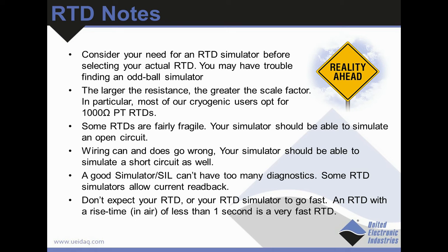Some RTDs are pretty fragile. You have to be a little bit careful. For that reason, your simulator should be able to simulate an open circuit. Again, your system should be able to recover or at least warn that you have a broken RTD, and you need to be able to simulate that. And again, wiring can and does go wrong, so a simulator should probably also be able to simulate a short circuit.